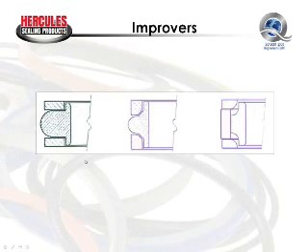Here we see another improver. This is a T-seal. T-seal is an evolution of the O-ring. A T-seal occupies the same amount of space as occupied by an O-ring, but it has two backup rings built into that space, which gives much better extrusion protection against the nitrile sealing element. It has the same sealing lip as an O-ring does, but it has a flat base, which gives a lot greater stability to the seal in the seal groove.